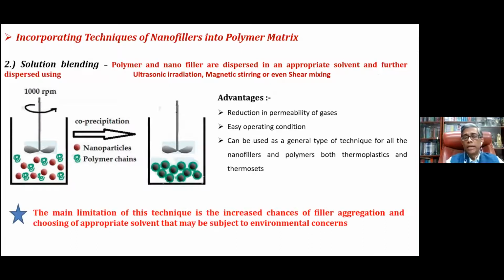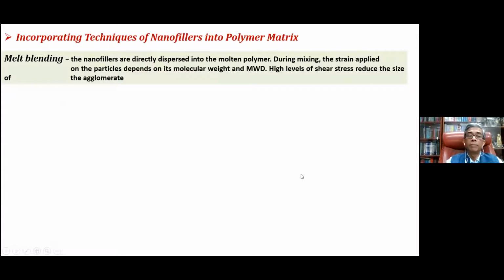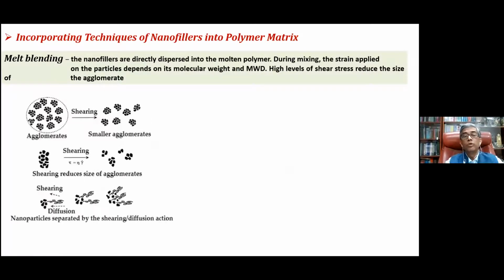In solution blending, we can have easy operating conditions and gas permeability, but this actually needs removal of solvent, which can be an environmental concern, and then aggregation may happen. This is the way we do melt blending, and this is a very enormous job.